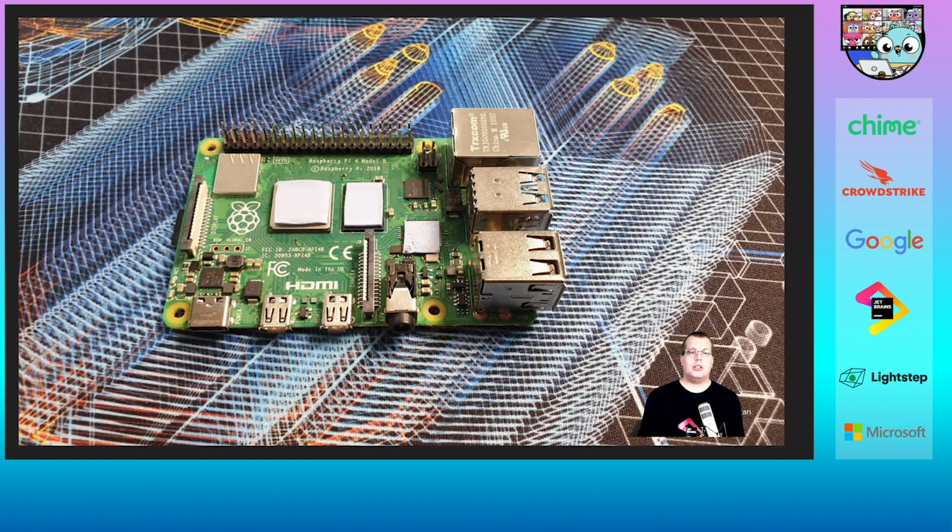If you want to have a look at it a bit closer, it looks like this. This is where the CPU or the SoC is. This is the memory, and this is the Ethernet controller. The GPIO part, it has an Ethernet 1 gigabit a second connection, 2 USB 3, 2 USB 2s, 2 mini HDMI outputs, USB-C power, and display and camera connectors.